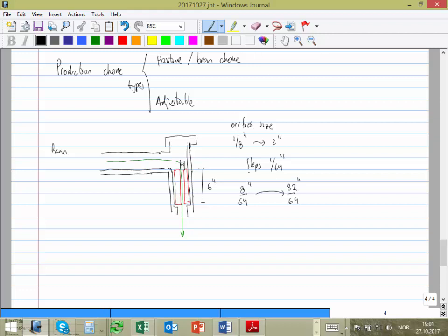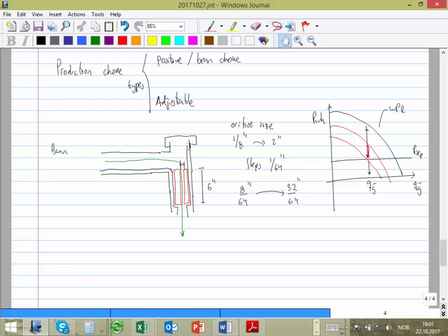And the point is, remember the intersection. I'm not sure if you already forgot, but we had something called WPR, wellhead performance relationship, and we had a P separator, and a rate that we wanted to produce, and we had this delta P choke. But with depletion, and we'll see if next week we can make an exercise on that, the WPR goes down, so at every time step you have to open the choke. And if you have this type of system, you have to physically go and take out the bean and use one with a bigger hole, of a bigger size.